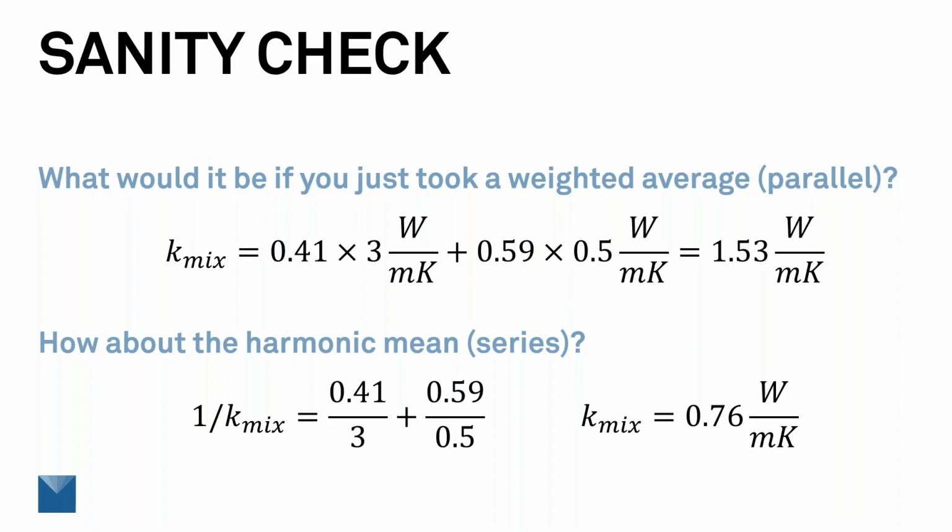And so the tendency is for the soil to dry out around the cable. If we had just soil around the cable and it dried out, we saw in that early graph that the thermal conductivity would go down to something like 0.2 watts per meter Kelvin. What would it go to in this mixture that we have here?